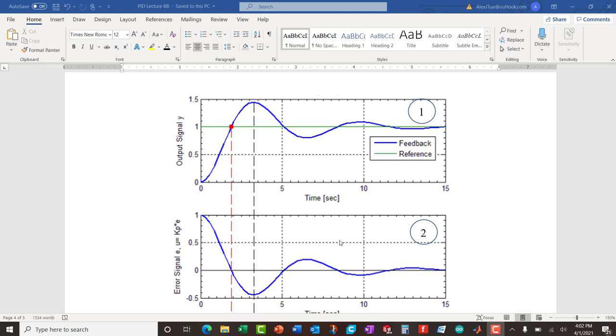Okay. Now, if we, for argument's sake, say that the value of Kp is 1, then the proportional controller is the same as the error signal. So let's just assume that for now so that we can see this is not only the error, but also our pretend proportional control voltage being sent to the motor. Now notice that when the ball reaches the center here in the green line, there is no longer any need for any voltage to be sent to the motor, right?